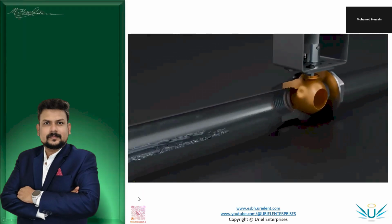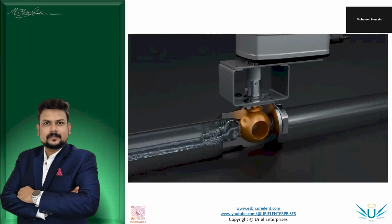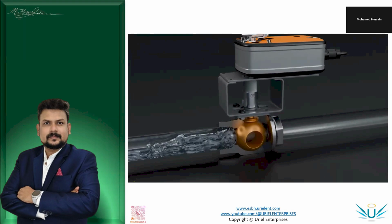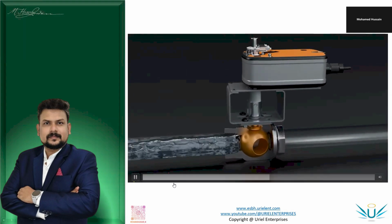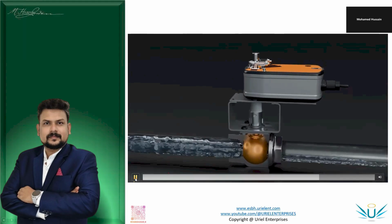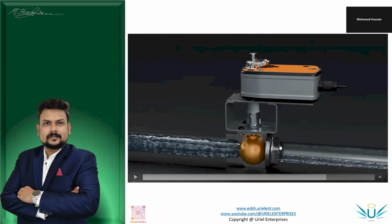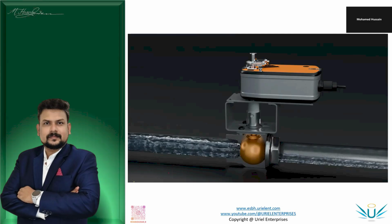Now remember all the things: valve coefficient, valve authority, pressure drop, and then the entire circuit pressure. Here they are calling the entire circuit pressure the pressure at the time of fully open. The water comes from the pump to the valve, then from the valve to the cooling coil, and after the cooling coil it returns to the pump. That small closed circuit pressure is known as the system pressure.